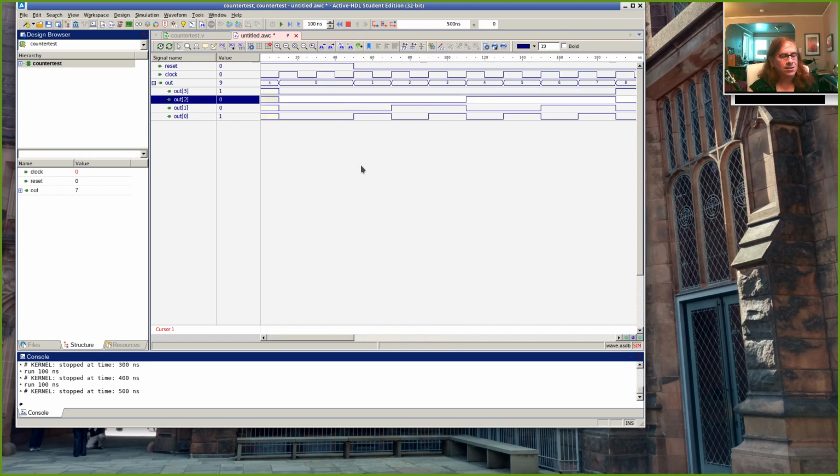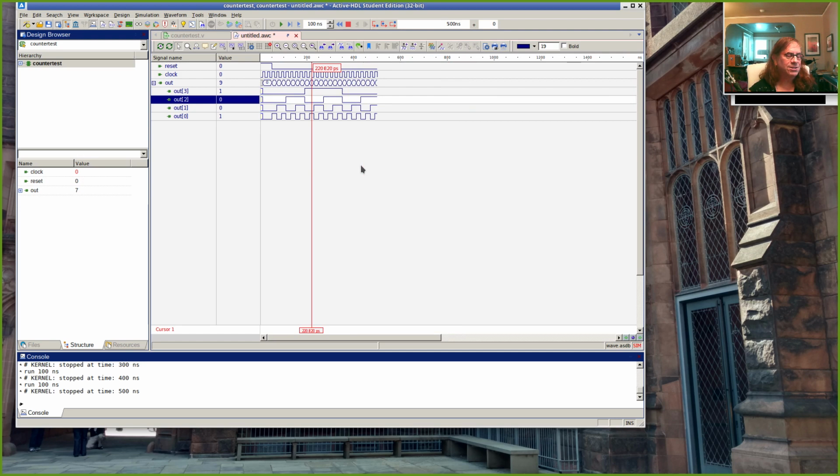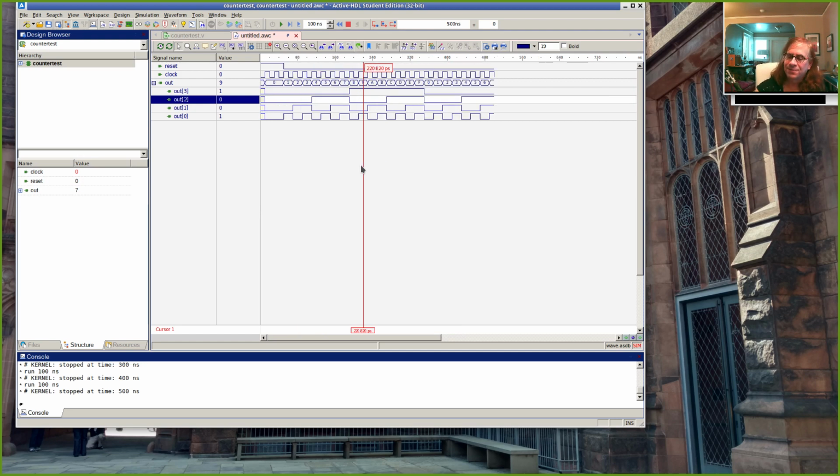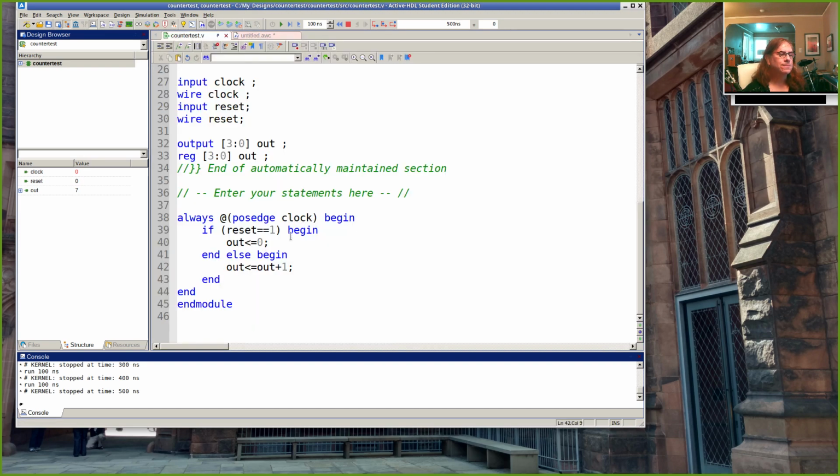So that's a counter, and to build this is a state machine, right? We have 16 different states the machine can be in, and each time the clock ticks, we move from, say, state 12 to state 13. It's a Moore machine where if we're in state 13, the output of our machine is the value 13. To build this, we'd need 4 flip-flops and a little bit of glue logic depending on the type of flip-flops. To set it up in Verilog, it's just an if-then-else.